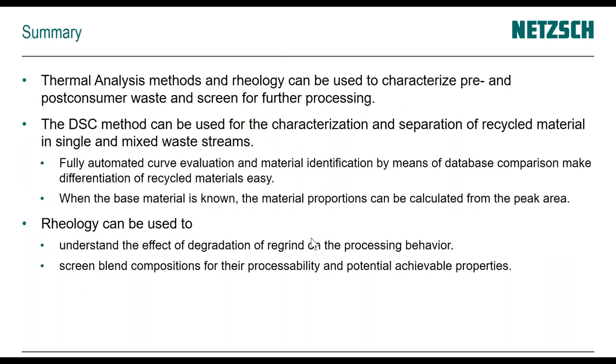So to conclude all of this, I hope I could show you that thermal analysis and rheology can be used to characterize pre-consumer and post-consumer waste, and it can help us to screen for further processing. The DSC method, hopefully I was able to convince you, can be used to characterize and separate recycled material in single and mixed waste streams.